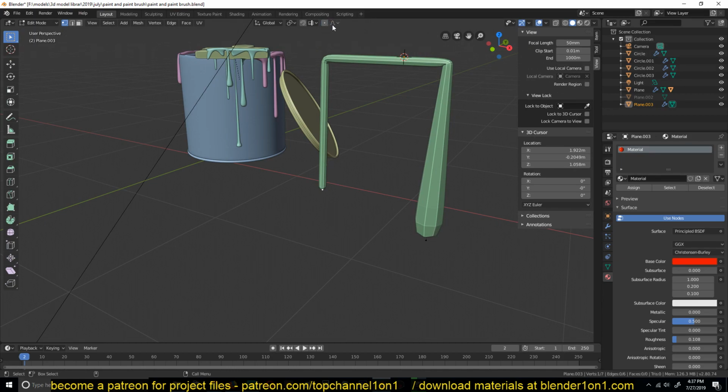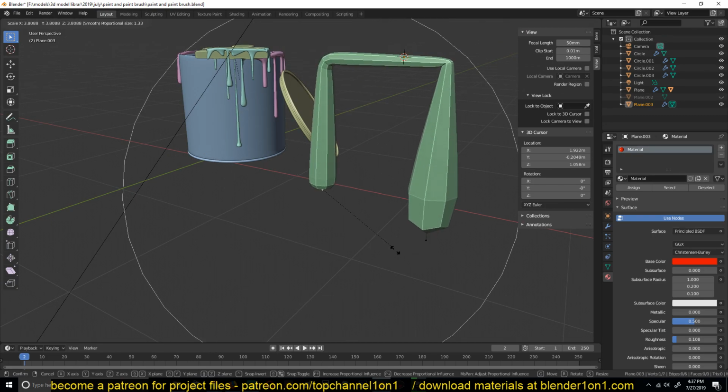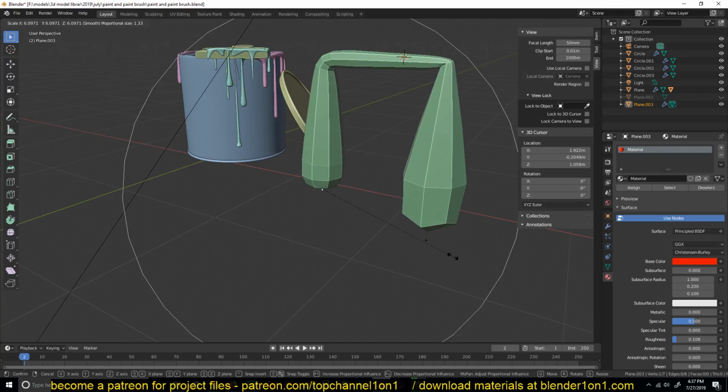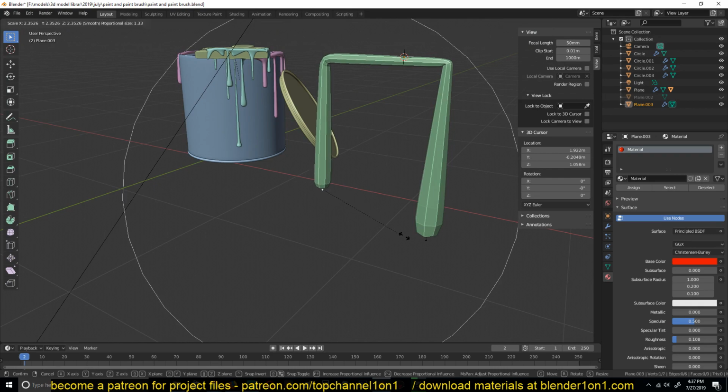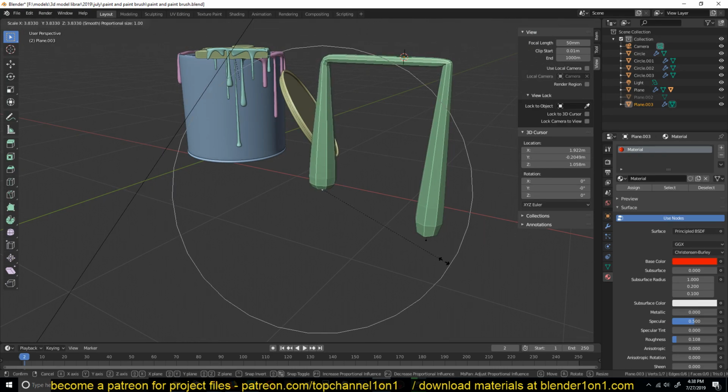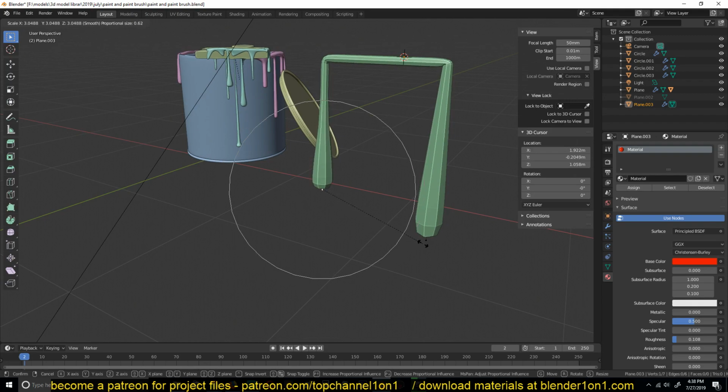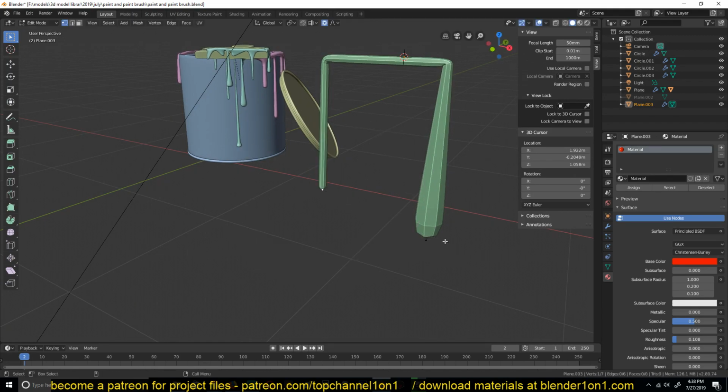If we didn't have connected only and tried scaling this, when we enlarge our proportional offset, you can see it's also scaling up this part because it's being enclosed in our offset. So you want to turn on connected so that we only scale up what is connected to this teardrop, and you can see the shape we get.